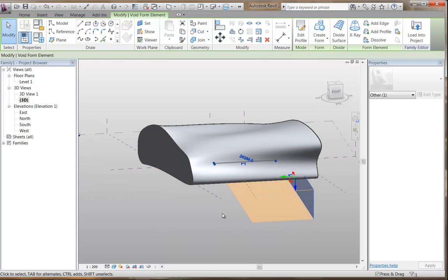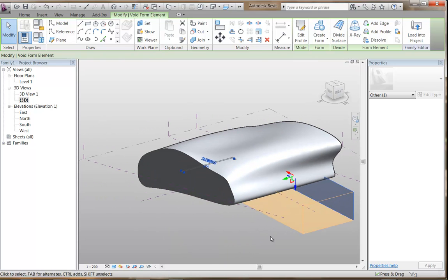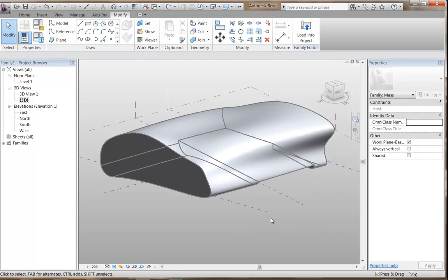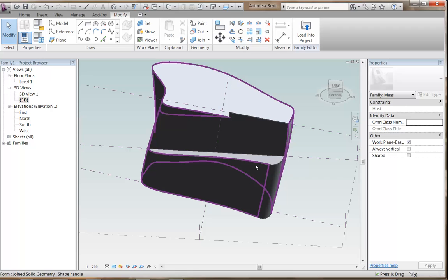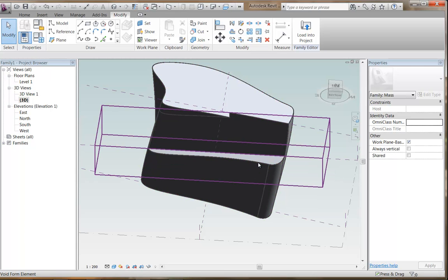But I want to show you a couple of things that you can do in Revit that you couldn't do in the past. So now I've just deselected it, and you can see it is cutting away part, but I want it to cut away more. Right, so I'm going to just select it. Now, if you haven't used Revit very much, it's handy to always remember the option key is Tab. So there, on the edge of this void, I don't get my void. Tab though, and enough times, it'll give me the object at the edge of that, and that's the void.